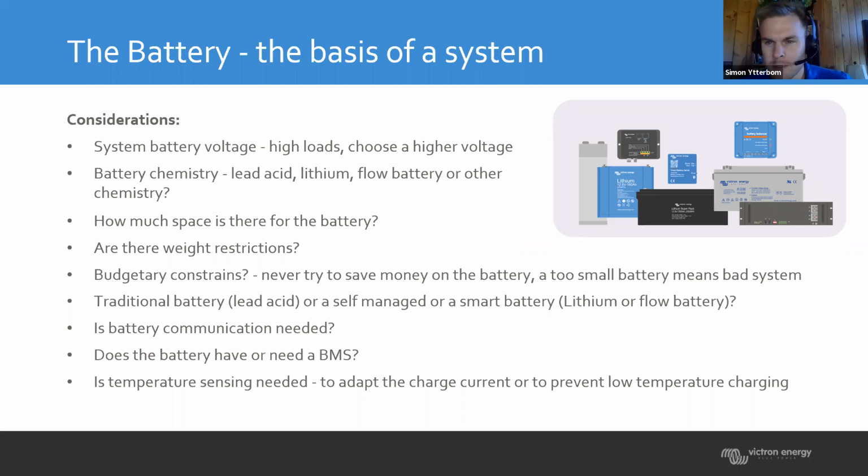If, for example, you have a 1200 watt load like the microwave and you're running that on a 12 volt battery through an inverter, you're going to consume about 100 amps. So you need to have cables that can hold 100 amps, and you need to have fuses that hold up to that. If you do the same load on a 24 volt system, then you would have 50 amps going through those cables. So your cables are smaller and your fuses are smaller.